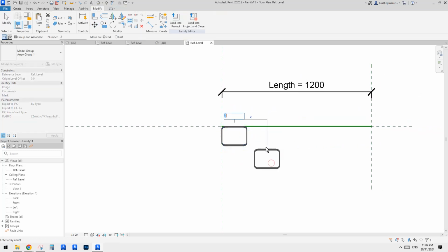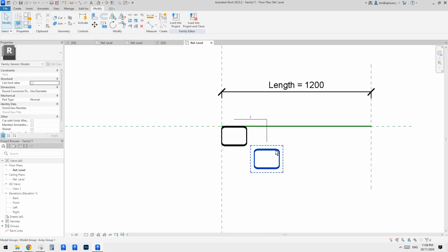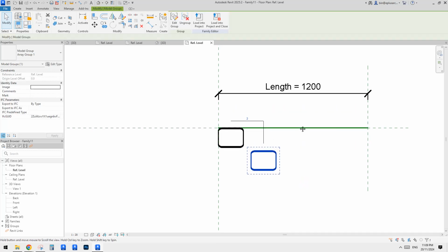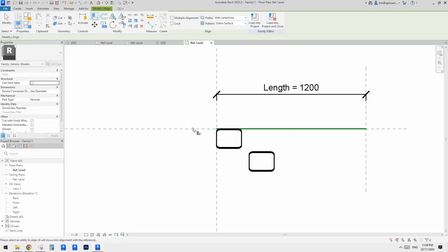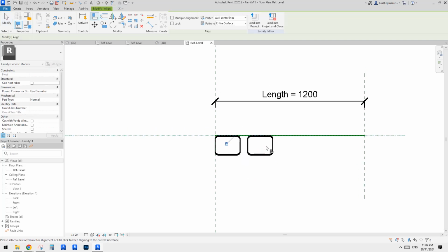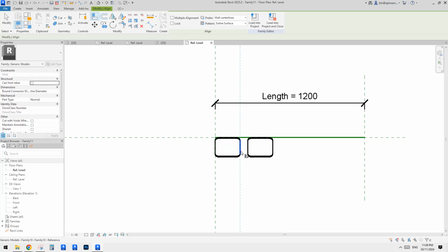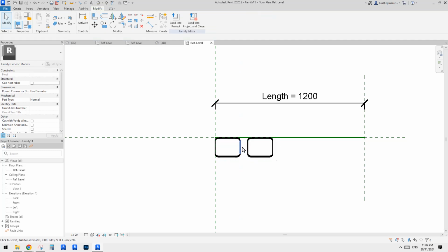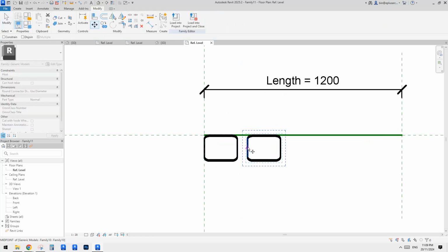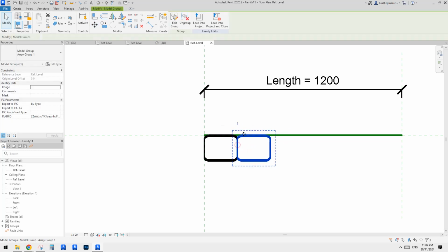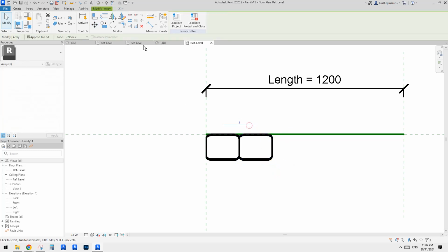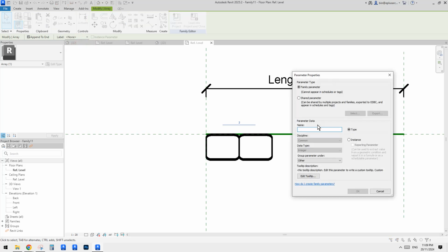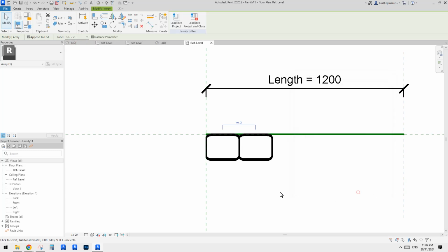So I like to place it roughly, just off the direction first, because it's easier for me to then try to lock it back, right? So and same here. For this one, actually, I don't think we need to lock at all. So just leave it like this. We just need to create a parameter for this number. So let's add a number. So I'll call it NO dot and an instance and OK.